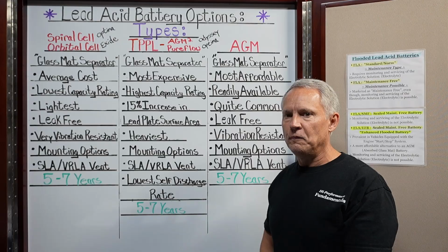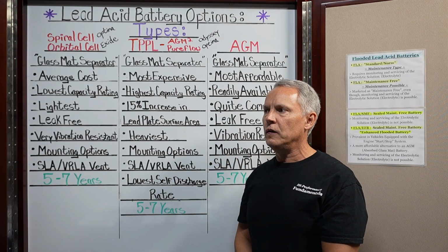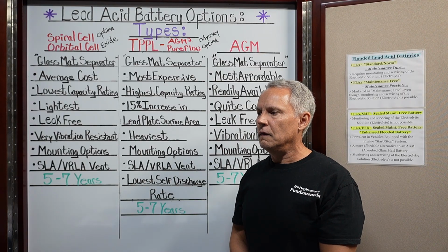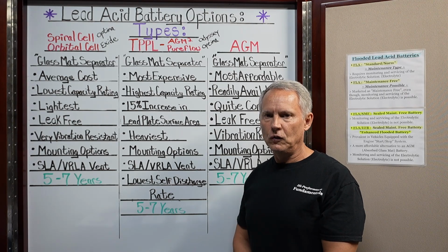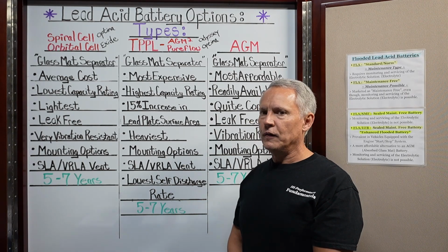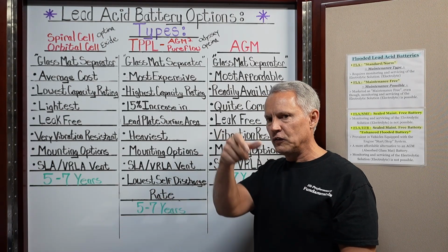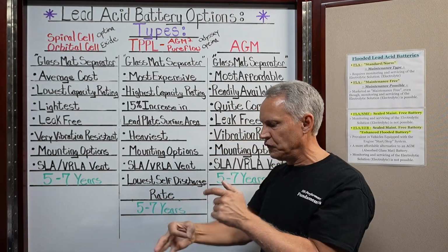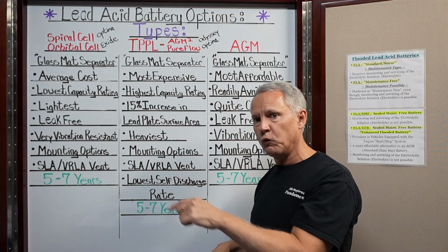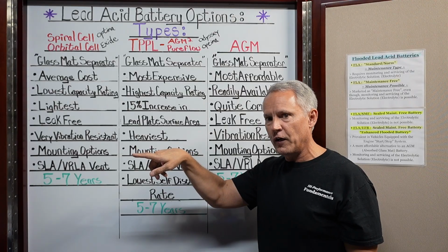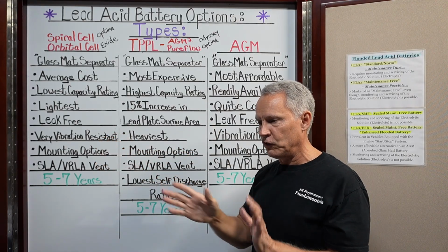And there have been times, and this is absolutely no exaggeration whatsoever, I want you to understand, that the corrosion from the lead acid batteries cost the customer a couple of thousand dollars. Now, I understand that sounds ridiculous, but if the corrosion crawls down the cables, it's not just on the terminal. You open the hood and you see the corrosion on the terminal, on the cable. But if it crawls into the insulation and starts working its way over to, let's say, the power distribution center under the hood, or down to the starter motor, or up inside the firewall, it starts to creep.